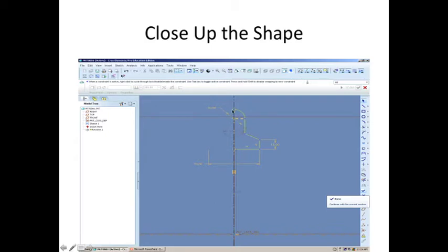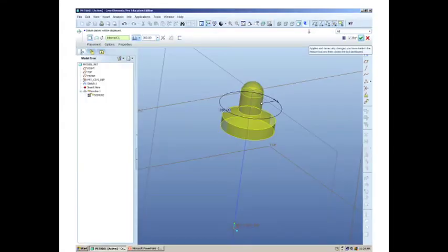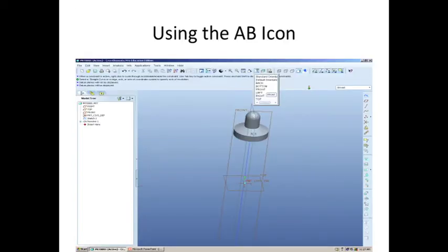You're going to want to delete everything, because if you don't, then the revolve won't work. So once you delete everything, which is that straight line we did, we're just going to make a brand new line. From there, we'll hit the check mark, and it'll look like this, and everything looks all good. Then we'll hit the check mark again, and there it is as a solid.